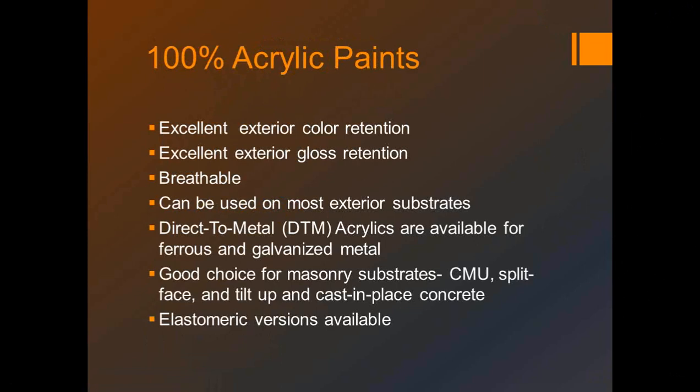Now, the DTM products, do they require a primer? Or is that the point, they can go on without a primer, just two coats? You can put them over a shop coat primer. If you have doors and frames, things of that nature, if they come on the job site and they have a factory primer on there, you can go directly to that with a DTM primer, a DTM finish coat.